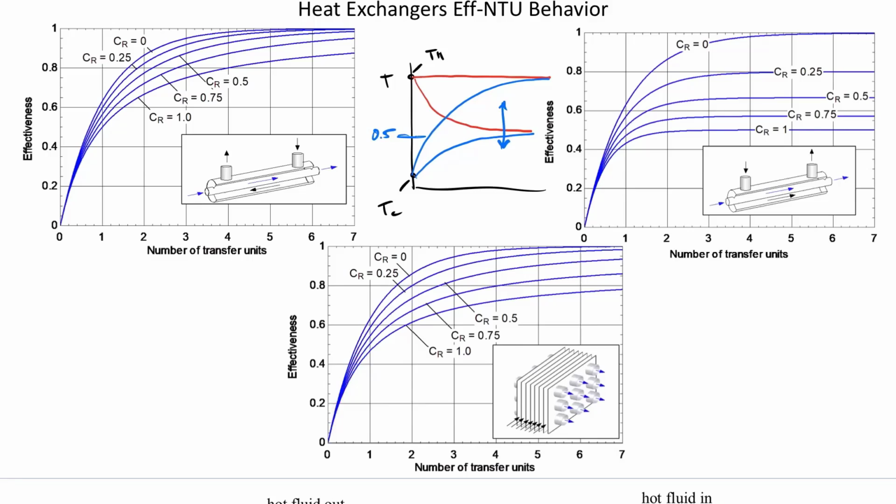If you design your heat exchanger and you're finding NTUs like 50, that says something about the design too. It says you're kind of wasting your money on your heat exchanger. You're all the way out here where an additional unit of heat exchanger is not actually changing your solution at all. Your effectiveness is what it is. It's not changing very strongly at all. So when you're designing, you almost always should find yourself in this kind of sweet spot, right around the corner of these graphs. NTU of 2, 3, 4, something like that. So this is a rule of thumb.